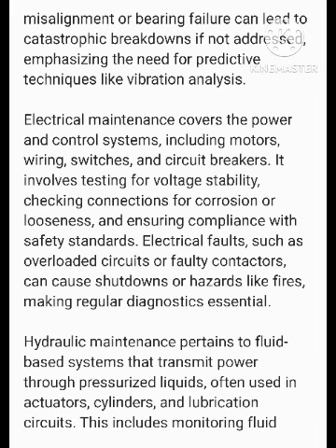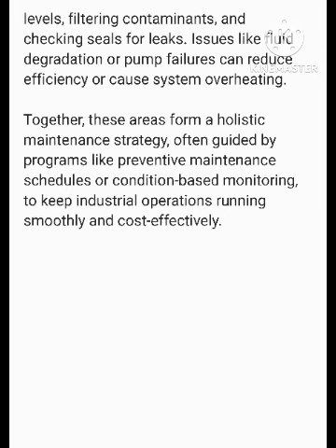Hydraulic maintenance pertains to fluid-based systems that transmit power through pressurized liquids, often used in actuators, cylinders, and lubrication circuits. This includes monitoring fluid levels, filtering contaminants, and checking seals for leaks. Issues like fluid degradation or pump failures can reduce efficiency or cause system overheating.